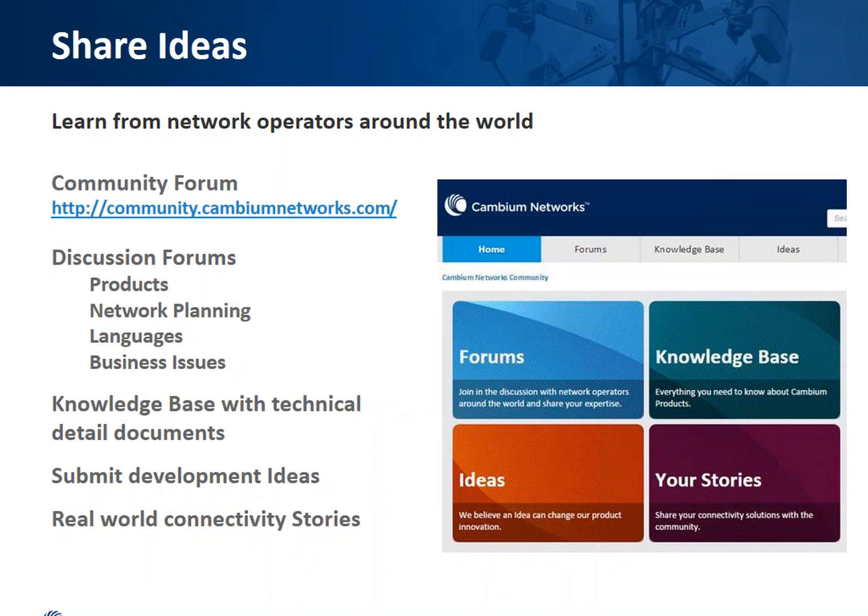You can take a look at the patterns. They're on the access point sector antenna spec sheet, which is available online as well. You can take a look at the patterns and see if that works for you. But I think you might be missing out on those in-betweens if you try to do a 3-sector deployment with the 65-degree antenna that we provide.